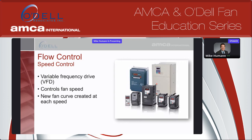Basically, as you change the speed, you create a new fan curve. Ten, twenty years ago, we saw a small percentage of fans having these, and now it's basically commonplace. In a lot of industries, it's basically required for fans to come on VFDs, and that includes belt drives. Obviously direct drives come this way, but even belt drives we see on a lot of VFDs now, just for flexibility.